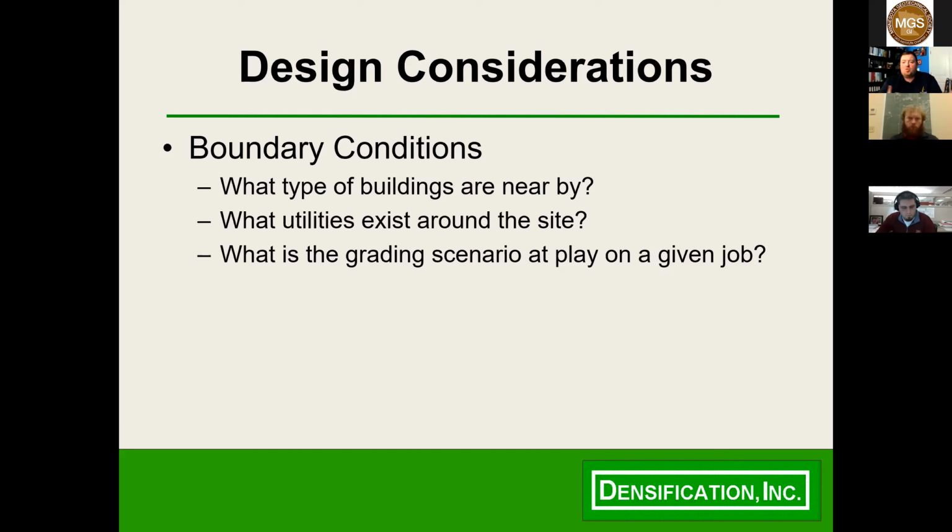Or are we in an industrial zone where you've got another warehouse a couple hundred feet away and it's something you can manage, right? So that is a very important thing. I may have the perfect soil conditions on a site to implement dynamic compaction, but if it's for a school that's going in the middle of a neighborhood, sorry, call the aggregate pier guys, because it's not a good scene for everyone at that point, right?